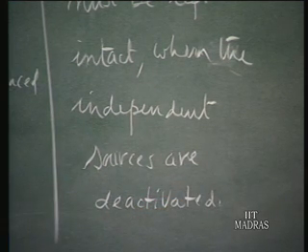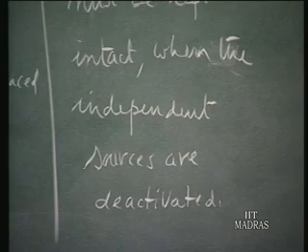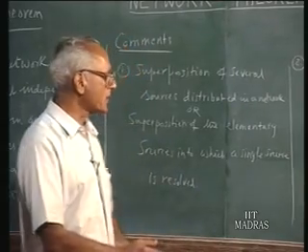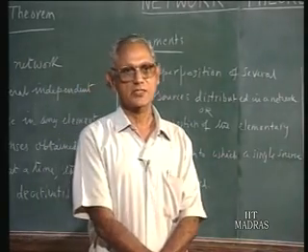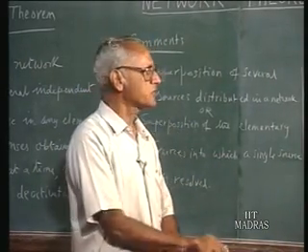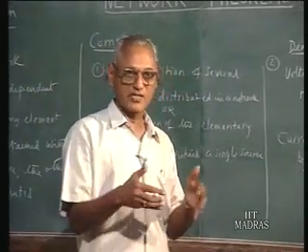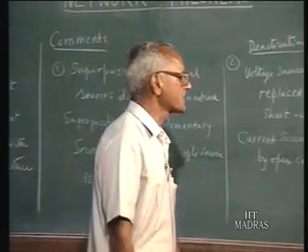So that is important. If you have dependent sources, those dependent sources must be allowed free play as far as computation of the effect of one particular independent source is concerned. Dependent sources should not be disturbed, they should be there. Of course, their value depends upon the particular situation in the circuit.